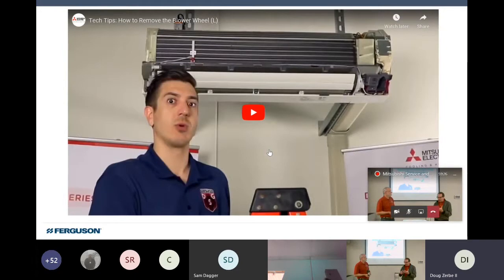The other thing is we mentioned the big filters in the front being done every other week. Those can be washed. They have about a 10-year life expectancy. The smaller filters do not get washed. Right. If you read the consumer guide, they are actually recommended to be vacuumed, because they are basically a paper product and will degrade much quicker if they get wet. Yep, and they are basically only good for a year.